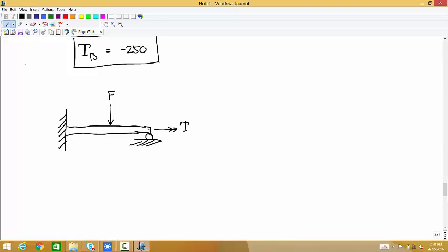And so that's the kind of problem you can do. There are just a lot of cases where your joints aren't restricting the degrees of freedom to the minimum that they could be. And for statics, that's what you need: in order to solve it by statics, you need your joints to be providing exactly the amount of constraint that's required.